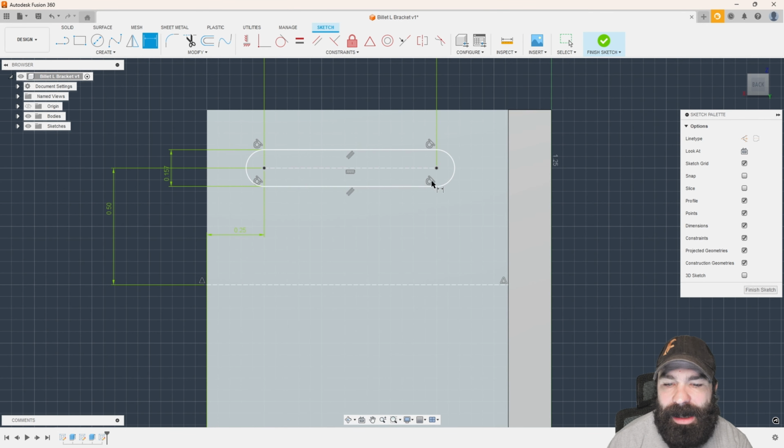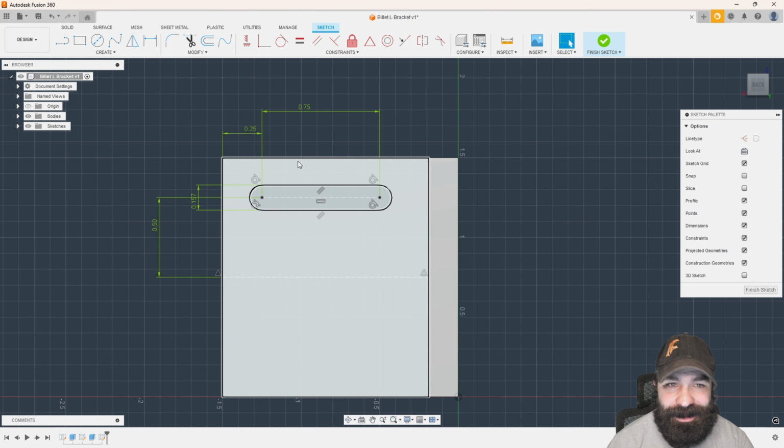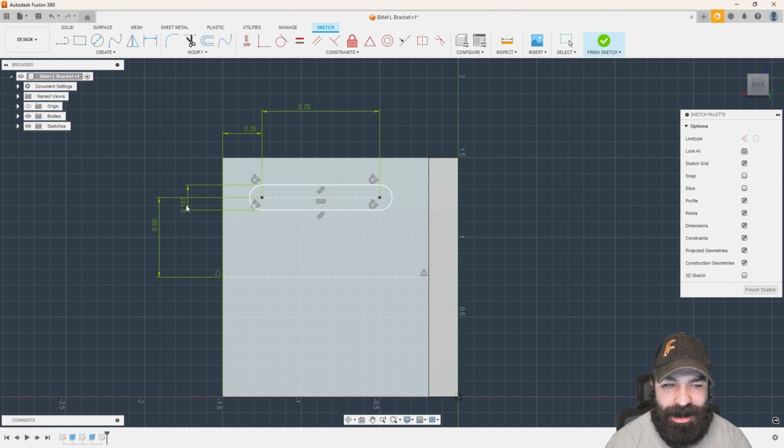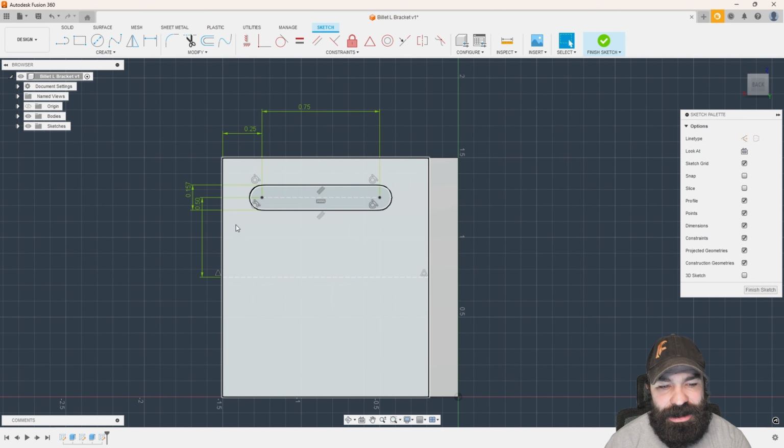And as you're seeing, all my lines are turning white. Yours should be turning black as they're fully constrained. Again, I just have a different background on for my parts. That's all I'm working with here. But again, as we've now fully constrained this, I'm going to drag this dimension up, which you can click and drag dimensions, guys, to get them out of the way, maybe to see them better based off what you're working on. All up to you.